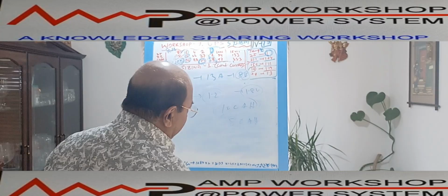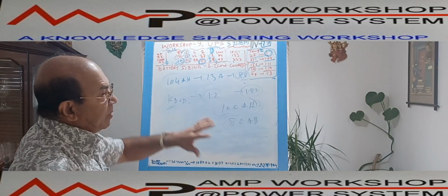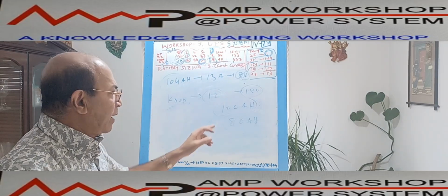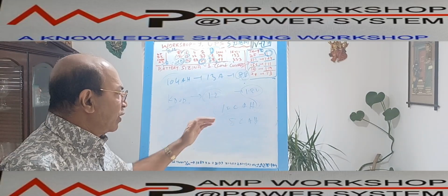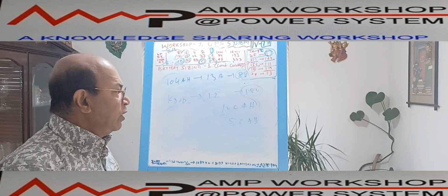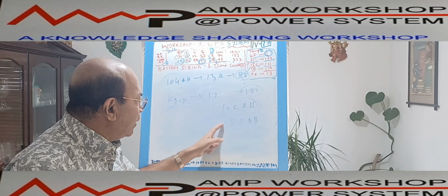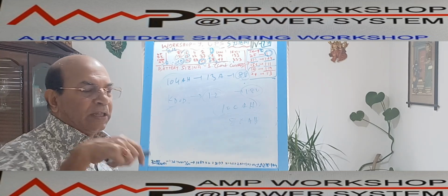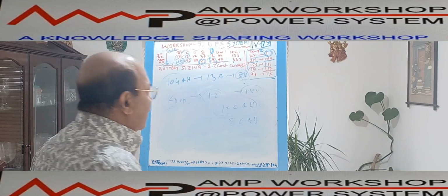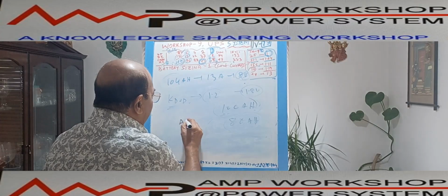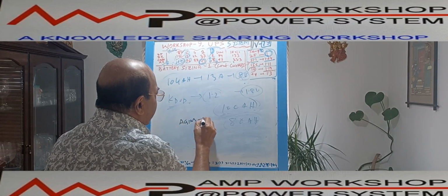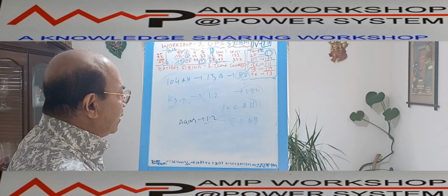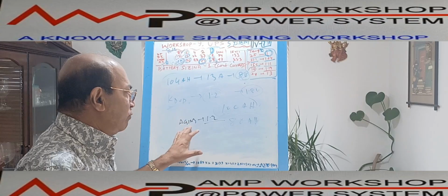In that case, when I am designing the battery, suppose this battery has a 20 year life, but after 10 years this has happened. So for the rest of the 10 years I cannot use this battery. So this additional requirement due to capacity depreciation, I have to include in the battery capacity calculation. That is what we call the aging factor. And most manufacturers say you put 1.2 as the aging factor. Then you will get the right figure. So this is another parameter to calculate the battery.